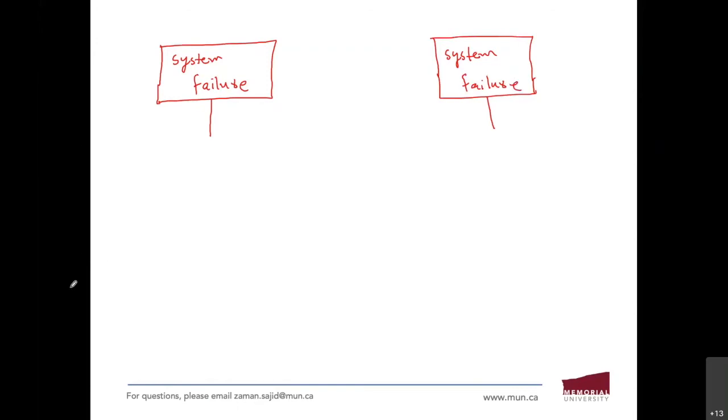Now, if I have the information, let's say, just leave some space here. If there are two events, E1 and E2, if I say E1 fails or E2 fails, how do we construct this in the fault tree? As you can see, I have either option. So E1 can fail or E2 can fail. According to the definitions that I mentioned in the previous slides, we will be using the OR gate here. Now I will draw my OR gate here because the information is showing me that either E1 can fail or E2 can fail. This is my OR gate symbol here.